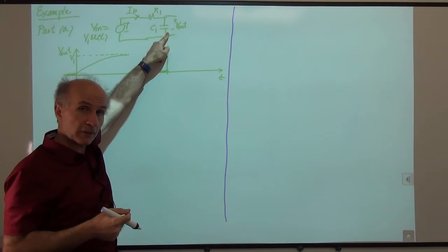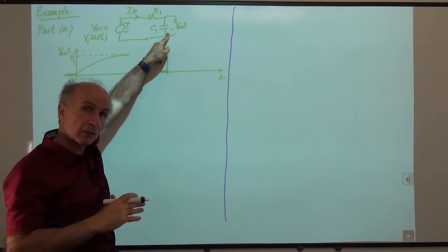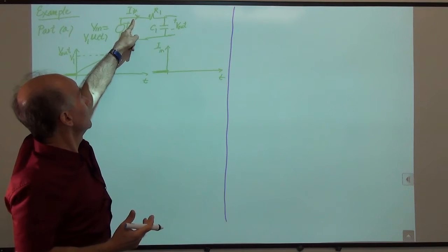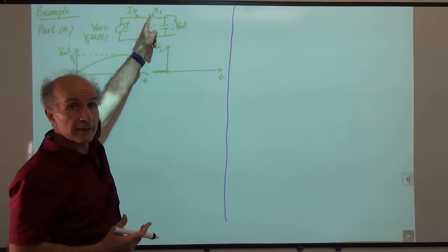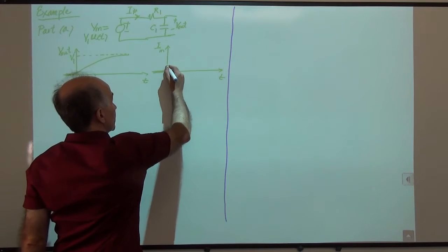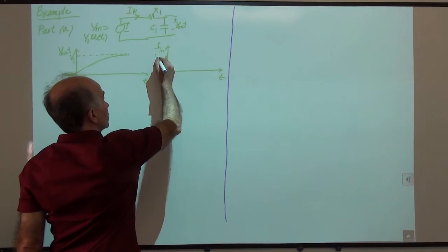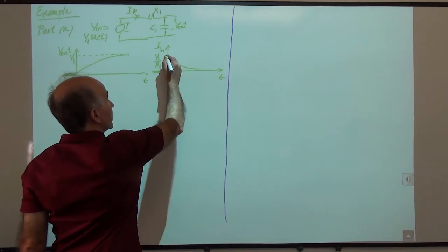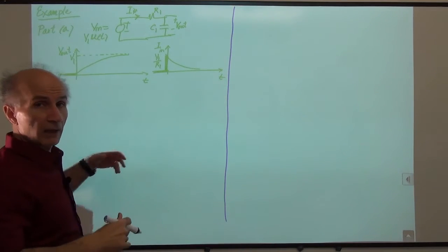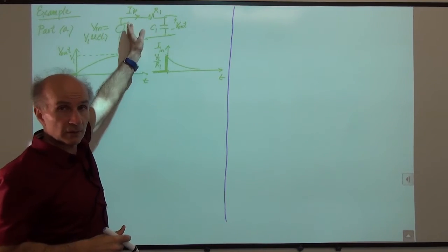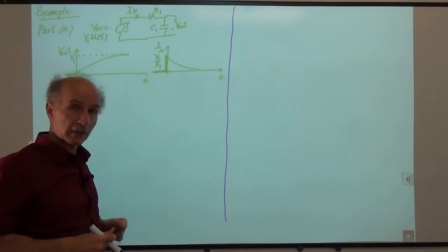So the voltage on the capacitor cannot jump, it has to stay at 0, so it's like a short circuit. So we see that this is 0, this is V1, so the current through R1 is V1 over R1. So the current through the capacitor through the entire loop jumps to V1 over R1, and then it decays to 0. At time infinity, all the voltages have stabilized, the current through the capacitor is 0, the current through the resistor is 0, so the entire current goes to 0.